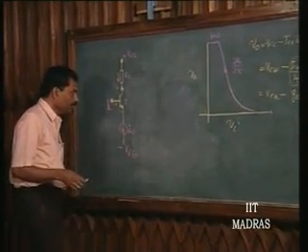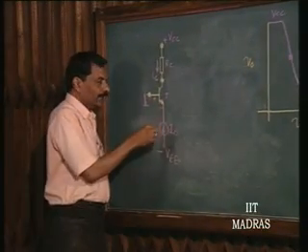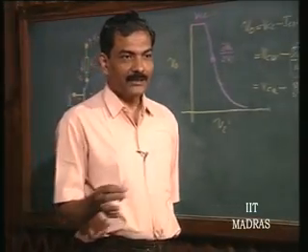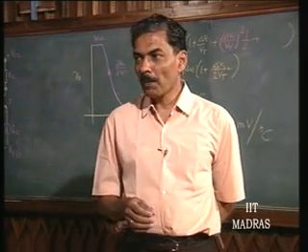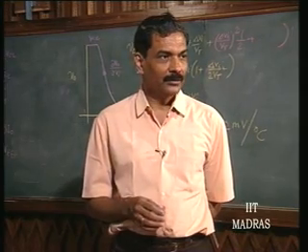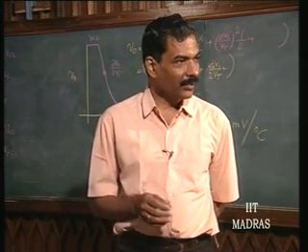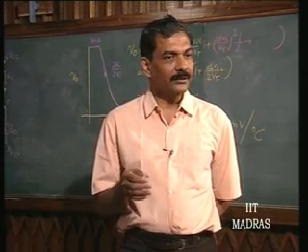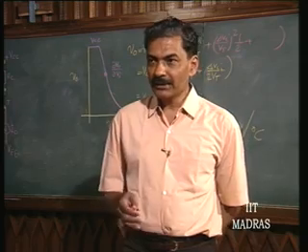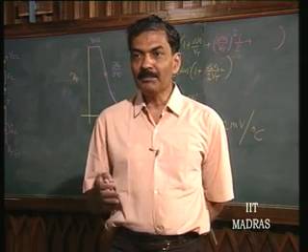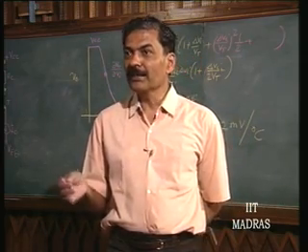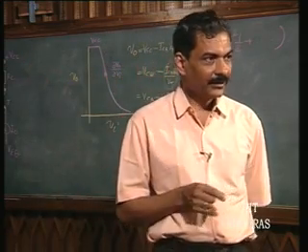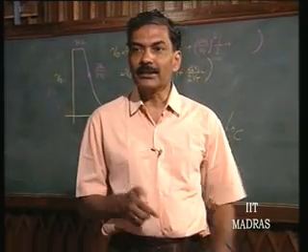Next, you will see that obviously the emitter has to be grounded, otherwise it cannot be a common emitter amplifier. So, how do I ground this? For AC it should be a ground, or for signal it should be a ground. So, normally in a discrete circuit I would have put a capacitor, which is called a bypass capacitor, but this capacitor for low frequency operation has to be very high in order to act as a short circuit at that frequency. But in an integrated circuit, what should I do?